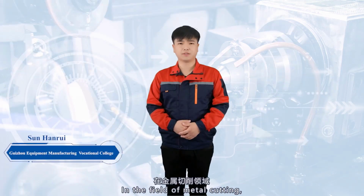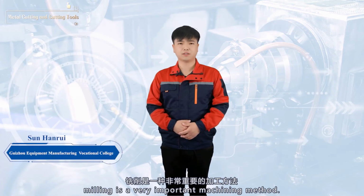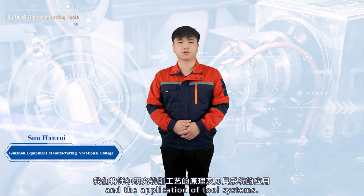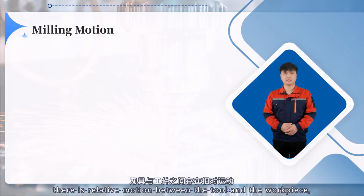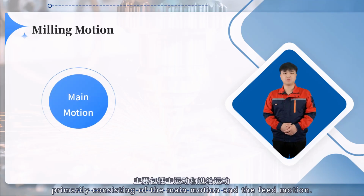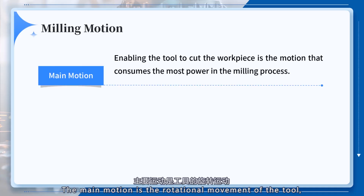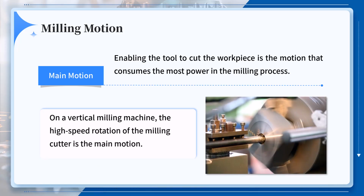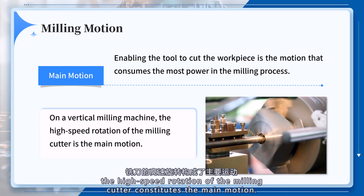In the field of metal cutting, milling is a very important machining method. Next, we will study in detail the principles of milling processes and the application of tool systems. During milling, there is relative motion between the tool and the workpiece, primarily consisting of the main motion and the feed motion. The main motion is the rotational movement of the tool, which enables the tool to cut the workpiece and is the most power-consuming motion in milling. For example, on a vertical milling machine, the high-speed rotation of the milling cutter constitutes the main motion.